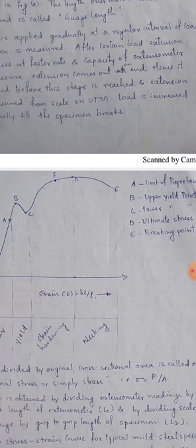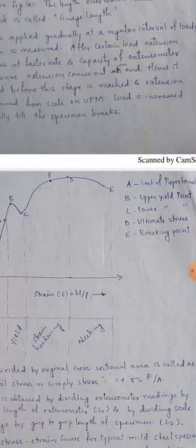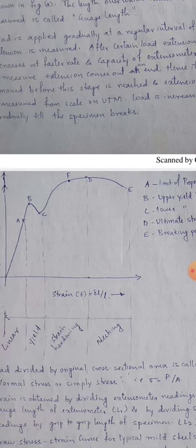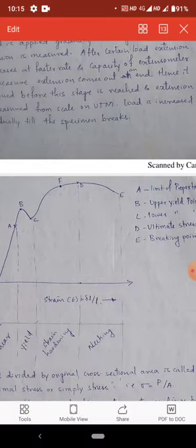When the load decreases, the material comes to its elastic position, to point C. Therefore, C is the lower yield point. Again, if you increase the rate of loading, there is a sudden change in variation of the stress as well as the strain.